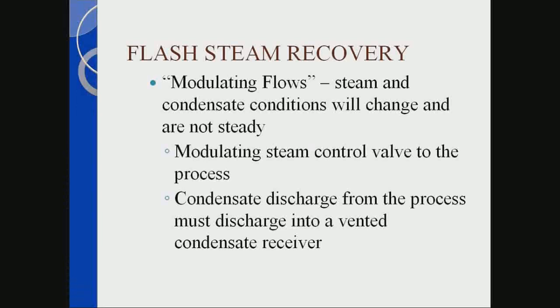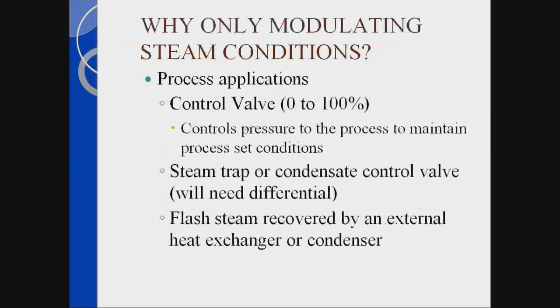Condensate discharge from the process must discharge into a vented condensate receiver. Process applications. The thing is, the control valve is going to travel anywhere from 0 to 100%. Really it's controlling pressure of the steam to the process to maintain process set conditions.